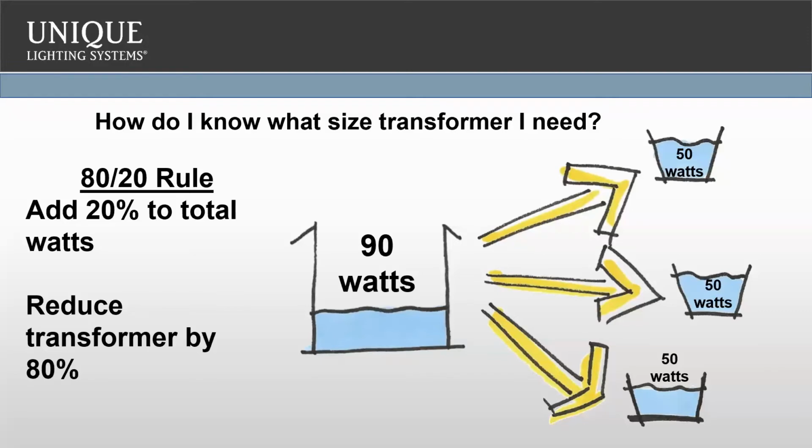Now, one of the things I like to talk with designers about is that lighting is probably one of the toughest things to deal with as a designer working with the end user, because once that project's installed, we lose complete control. If you design this thing right to its razor's edge, and that homeowner or project owner decides, hey, these 4 watts aren't bright enough, and runs down to Home Depot and buys 5 watts, he could start shorting out the transformer, or the wire. Or after the project's done and you've gone on your way, he goes to his maintenance guy and says, hey, why don't you add 5 more lights over in this corner? Again, if you're running at that razor's edge, you could start overloading transformers and wires.